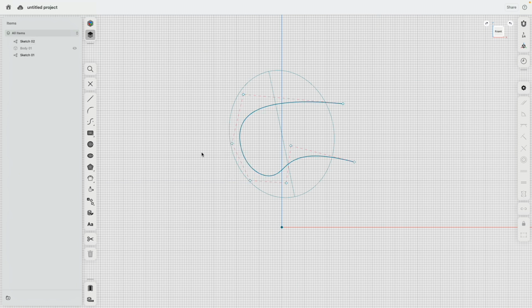However, we don't need to perfect this spline right now, because once we've created a basic 3D body, we can adjust the result by adjusting the sketch. Next, maybe a line that goes down, let's say to there, escape, and one line down here, and press escape. You saw I drew these lines on the splines.